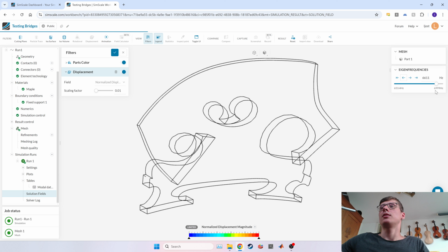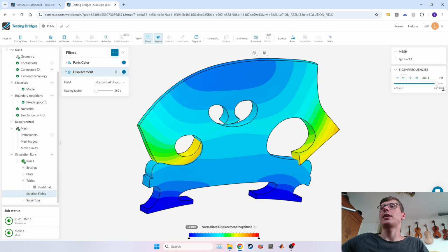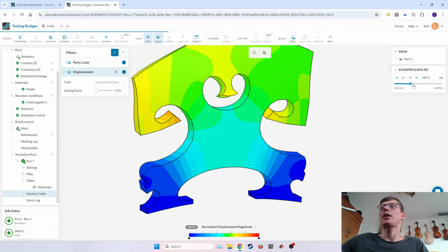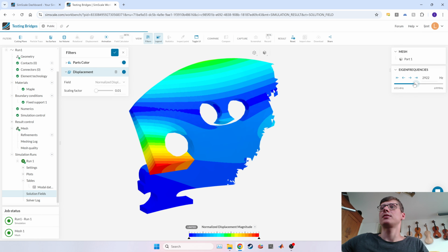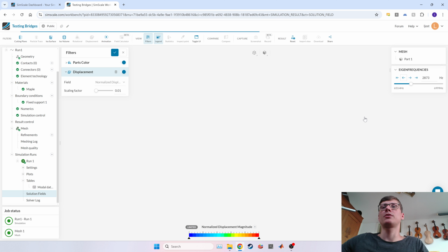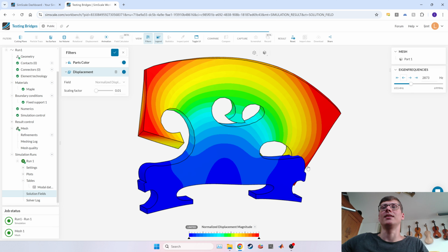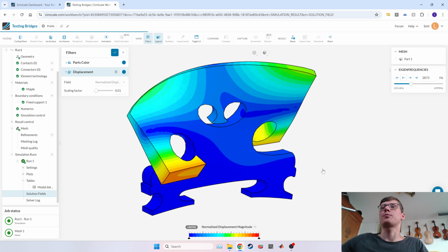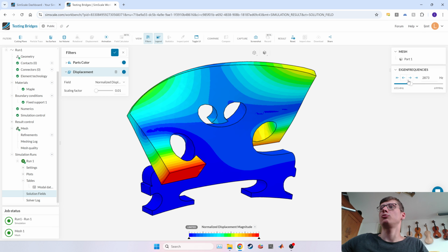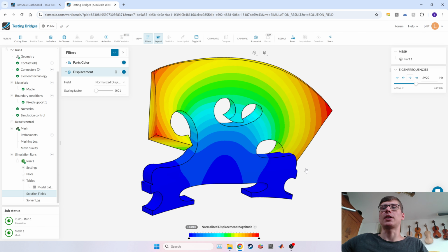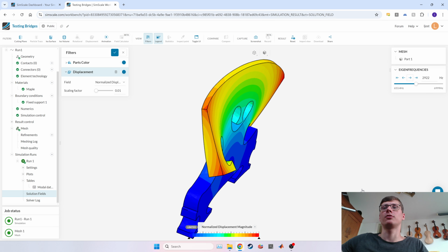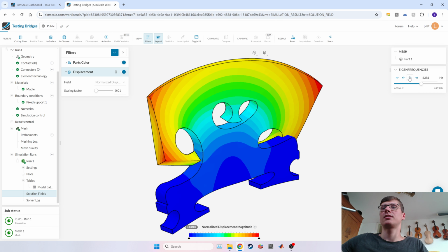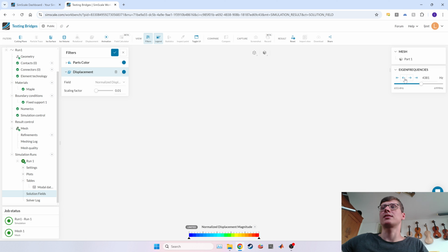So it found one eigenfrequency of the bridge at 6,999 Hertz, and then the next one down the list is at 6,600 Hertz, and it looks like this. And in this way you can go through it. And for example, maybe here we'll find the rocking frequency, maybe. Yeah, this looks like a rocking frequency of the bridge. Oops, I went one too far, I guess. Yeah, this looks like the rocking. Oh no, it's actually out of plane. It's a mixture, I guess.